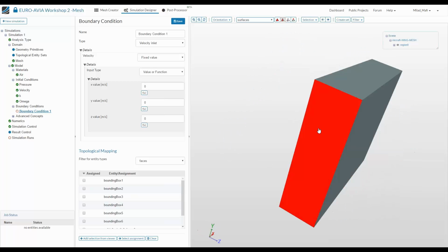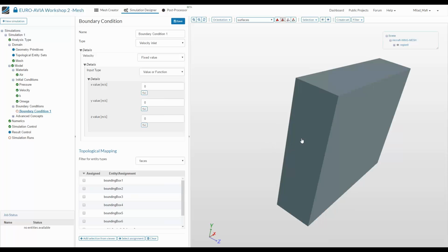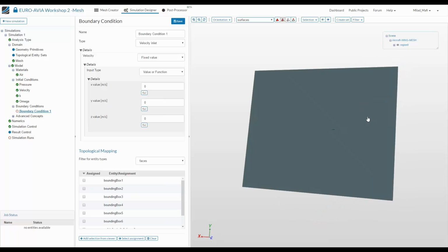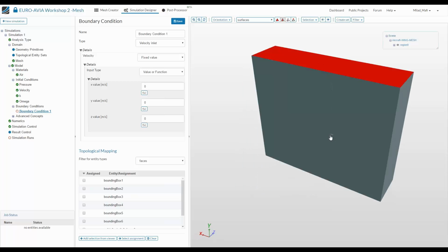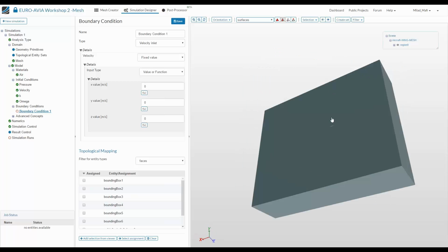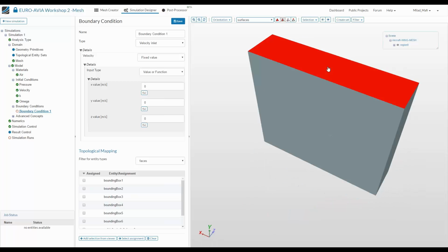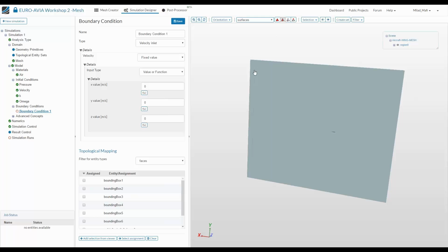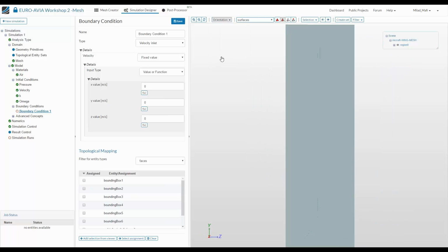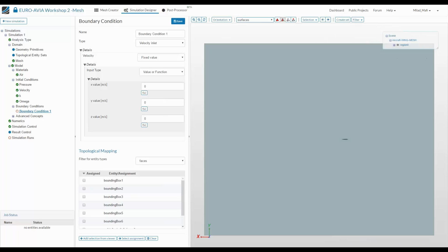First of all, since we have this angle of attack, we cannot assume this or that wall as a wall. They have to be dependent on the flow: an inlet, an outlet, or a wall. To give you a very simple example, if we would have this normal flow, we would make these walls closed.